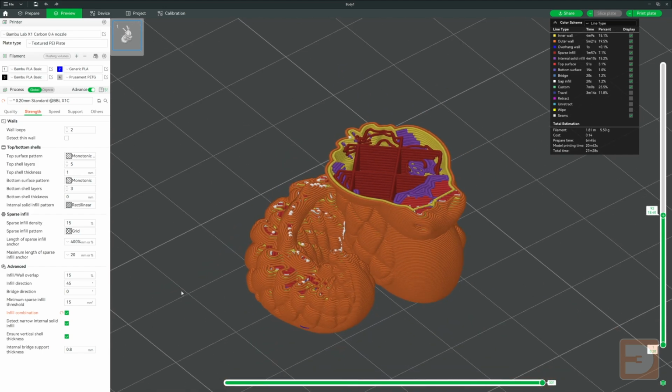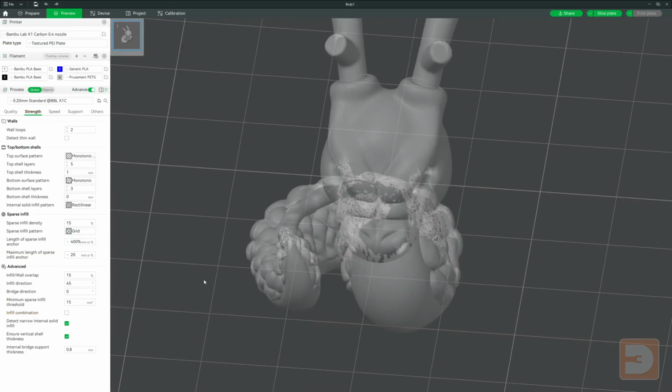This absolutely saves time as it's not printing infill every layer, but it may affect quality in some cases and won't allow you to print the infill as quick if you're already using a particularly thick layer height, as it's going to need to melt and extrude much more filament much faster. I'd suggest only using this if you really need to save time.